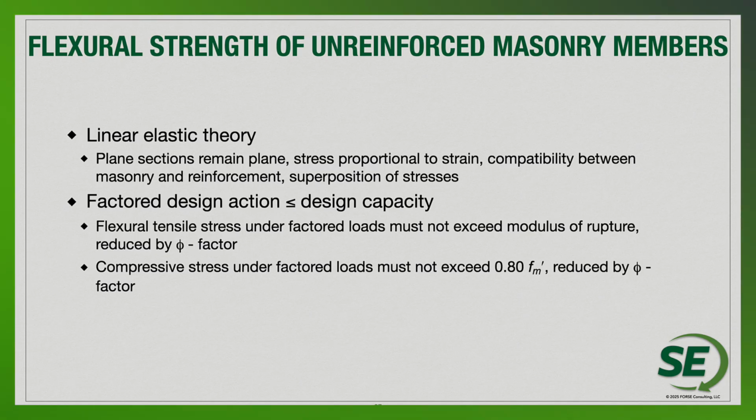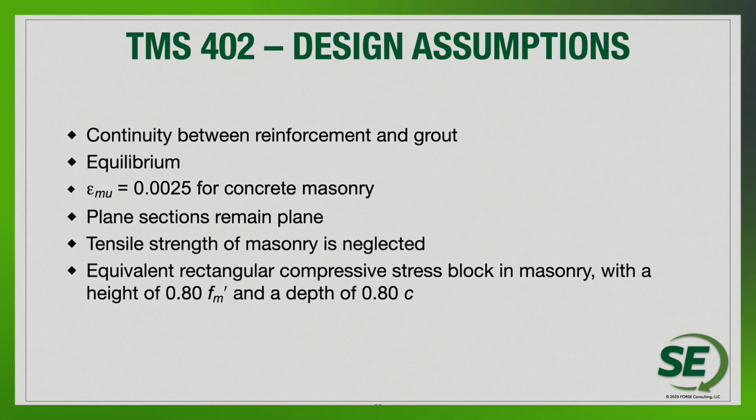Factored design has to be less than the design loads that you have for your design. So flexural tensile stresses under factored loads must not exceed the modulus of rupture reduced by that phi factor, and then compressive stress under factored loads must not exceed 0.8 times f'm reduced by a phi factor. So again, more design assumptions summarized here: continuity between reinforcement and grout, we have equilibrium, we have sections remaining plane, and then different compressive stress limitations.